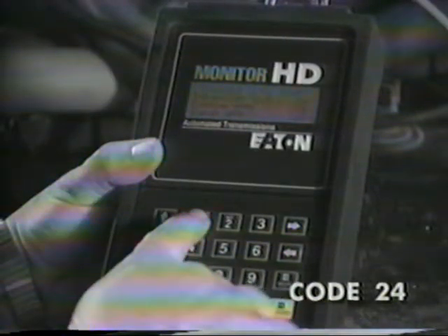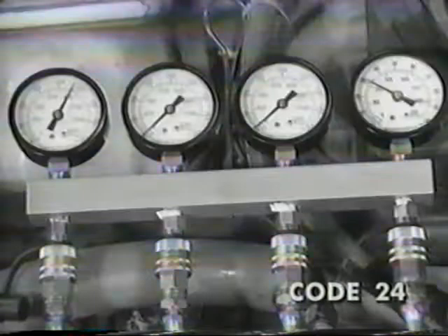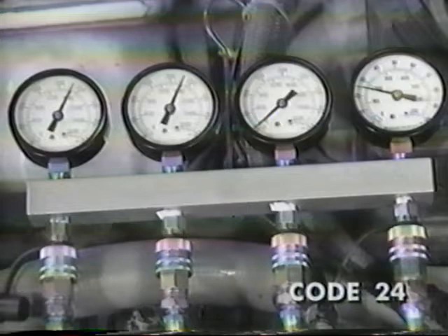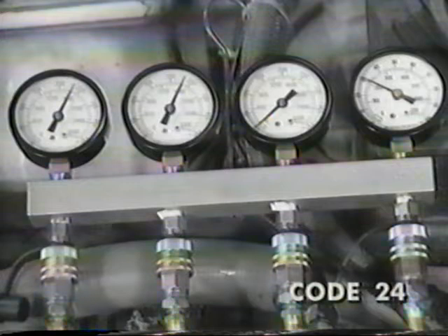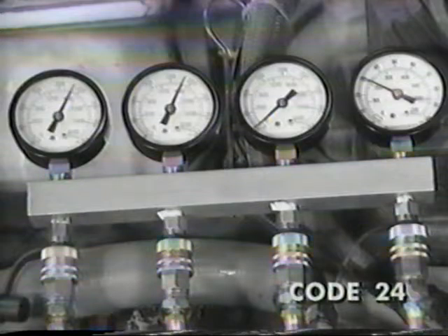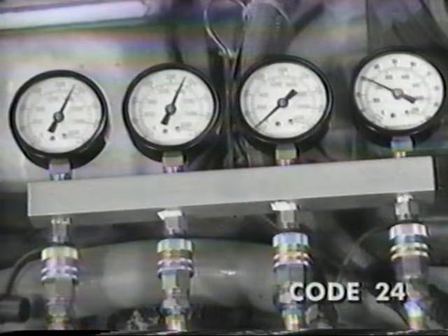By pressing and holding 1, you will activate the interrupt clutch test. Observe the gauges. They should indicate that main pressure is at 225 to 255 psi or 1550 to 1725 kPa. Interrupt pressure is at plus or minus 5 psi or 34 kPa of main. Bypass lockup pressure is 0, and lube pressure is 15 to 20 psi or 104 to 140 kPa. If any of the pressures are out of spec, replace the hydraulic valve.